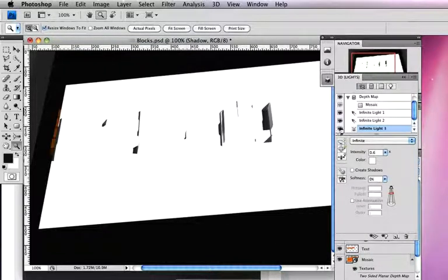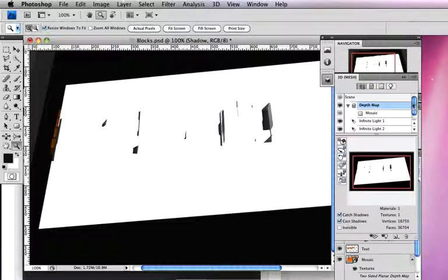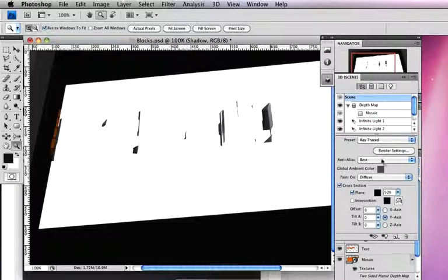So just like on the other layers, we're going to click on the little eye tool, and that should hopefully turn our layer off. As I said before, Photoshop does take a little bit of processing power to work with that layer. So as you can see, we start to get some shadows here. It hasn't worked out perfectly. I'm not sure why that is. I'm just going to make sure that we did set that to 4. Yep, it's on white. Mosaic we set to black, grey 1, white, black 1, 0 for glossiness, that's fine. And we are on ray traced and still on best.